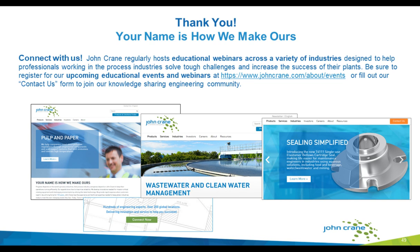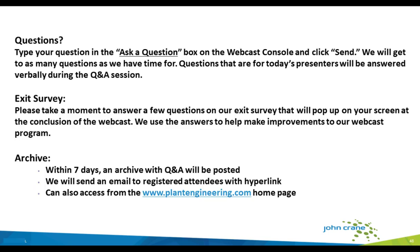Yeah, so in a dynamic lift USP seal, the seal faces are always loaded compressively by the process pressure. So they're always in compression due to the process pressure at the OD. The unique nature of the design allows for that pressurization of a lower pressure fluid between the seal faces, so we get that pressure spike that creates the separation in the dynamic lift.